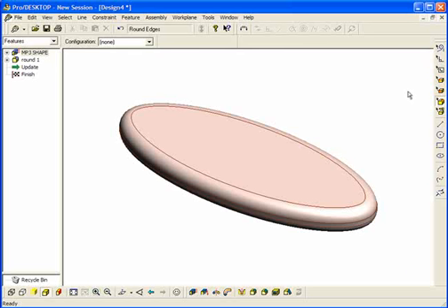The screen, of course, can be any shape you want. I will simply make a circular screen in the middle of the ellipse shape. The common mistake when making a new feature onto another surface on a shape is that you forget to make a new sketch on that face.